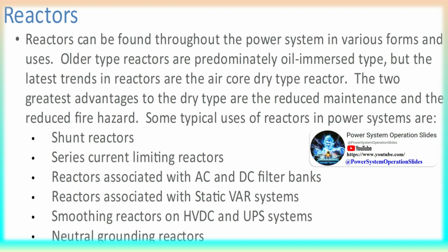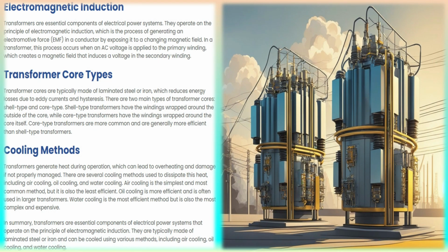Transformers are electrical devices that transfer electrical energy between two or more circuits through electromagnetic induction. A varying current in one coil of the transformer produces a varying magnetic field, which in turn induces a varying electromotive force EMF or voltage in a second coil. Power can be transferred between the two coils through the magnetic field, without a metallic connection between the two circuits.